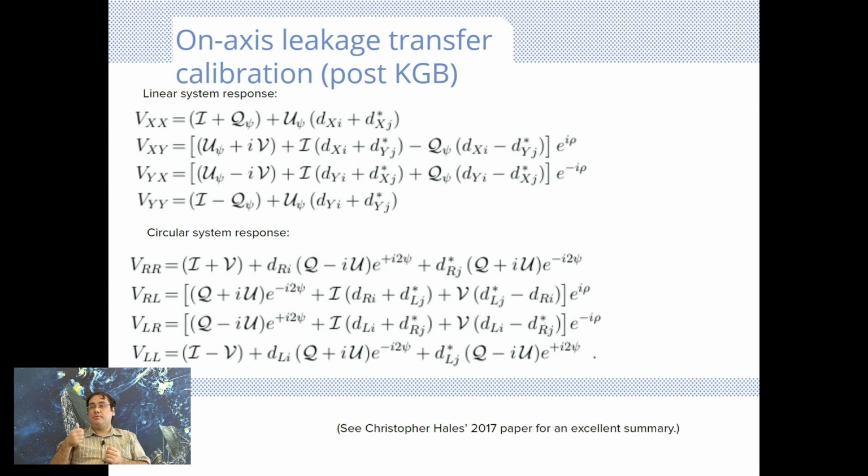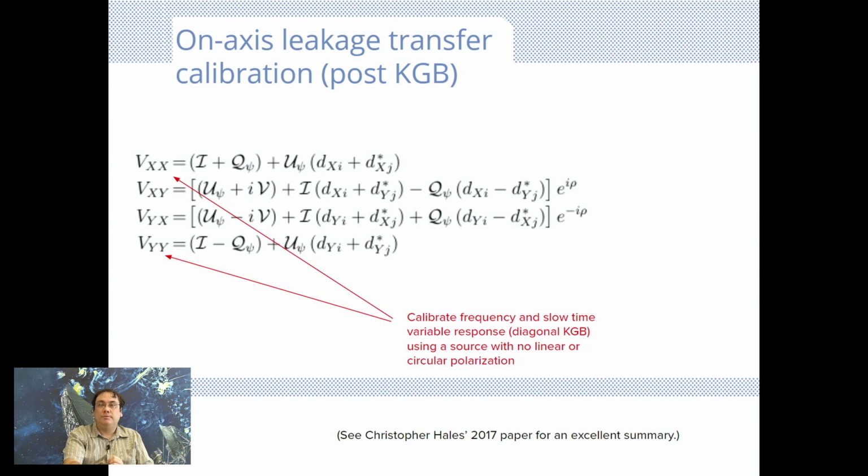Firstly, we need to solve for leakages, and secondly, we also need to solve for the delay difference that's introduced by the system on the signal that gives us circular polarization. That delay difference will take a signal that is inherently linearly polarized and turn it into a signal that is circularly polarized, apparently. So we need to undo that. So let's see how to do that.